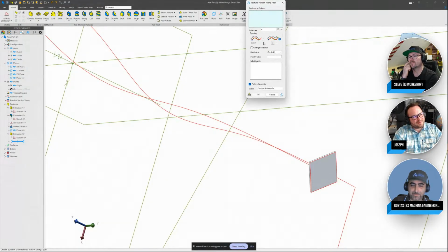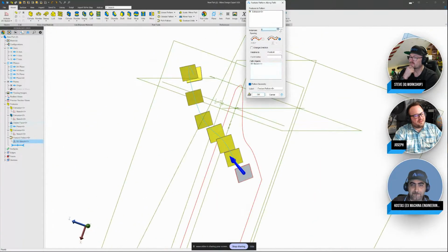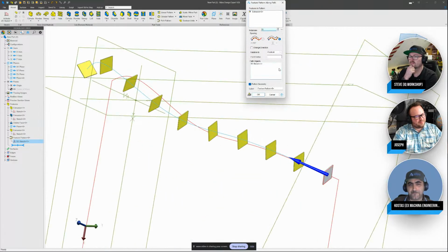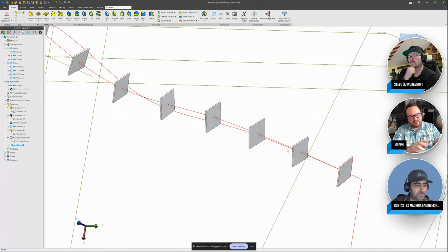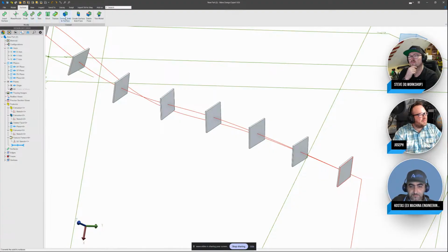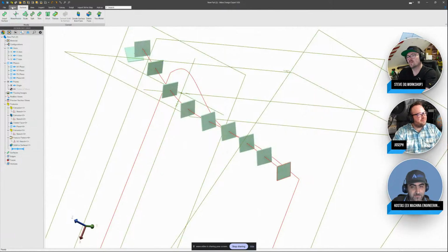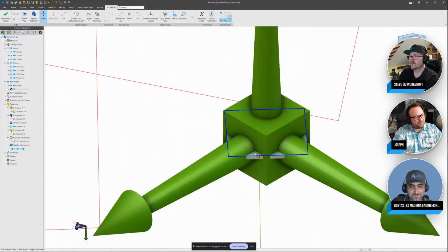I'm going to make a path pattern. We're going to pattern this extrude down this path. And just like that. Maybe I'm going to be a little bit smaller there. So we can tighten it up if we want a sharper angle, or loosen it up if we want a shallower twist angle. And now I can simply go to my surfaces and say convert to surface. All right, this is where the magic begins, although I hope it won't be too tedious for the live. I'm going to pick a corner here.